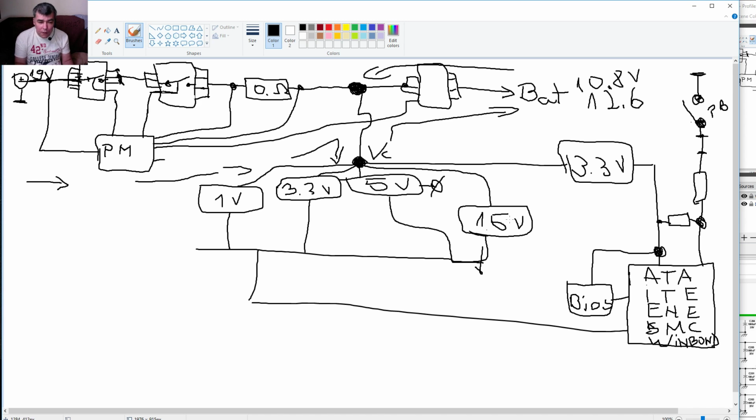First, check if you have voltage on the power supply, on that ceramic capacitor or on one side of the MOSFET, yeah? So you always should have 19. Yeah, the power supplies probably are not working, because the power supply will start working when you press the power button and this chip will start all my power supplies. Yeah?